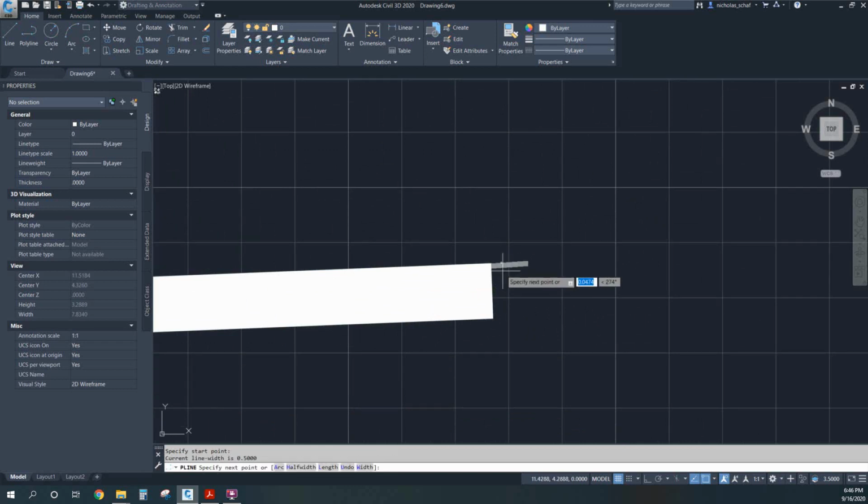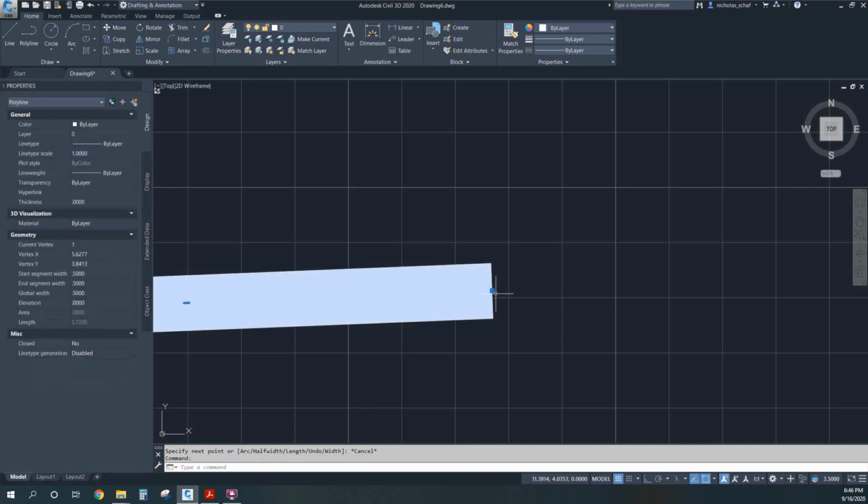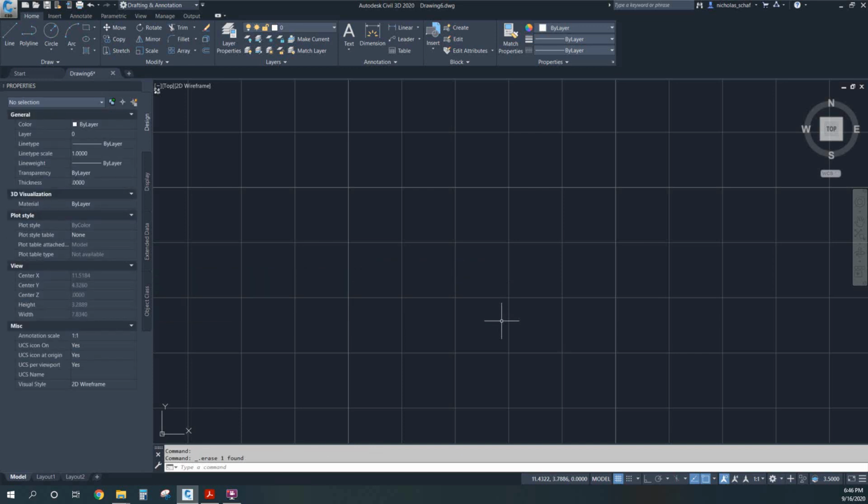So if you were to draw a line approximately, let's do half width, and I'm going to set it to 0, enter 0. Oh, okay, I made a mistake there. So half width, whatever you put in is the length that it goes in each direction of the center point of the line that you were drawing. In this case, I specified 0.25, so the center would be where this dot is. So it went 0.25 this way and 0.25 this way. So that's what half width does.